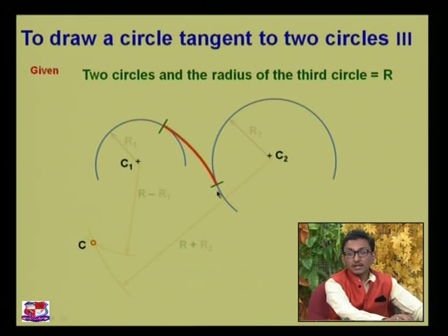This arc will touch and intersect only at a single point on each circle, at point number C2 and point number C1, which is our main objective. We need to draw a tangent circle to the other two circles, with radius equal to r. The final output can be like this. If you want to draw some arcs like this, then you must use this kind of method.